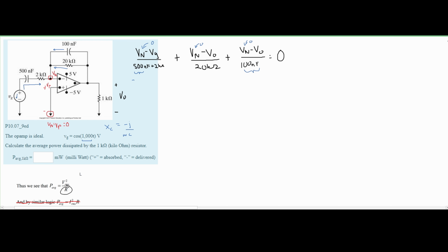We can write this as negative 2 kilo ohms, because the units is now going to be in ohms. That's what it would be when we do this conversion. And it's kilo because we have negative 2000. We know K is equal to 1000, and that's why it's in kilo ohms. Now we're going to look at the 100 nanofarad. It's going to be the same thing, negative 1 divided by 1000 times 100 times 10 to the negative 9th. And this is going to give us negative 10,000. We can also write this as negative 10 kilo ohms of resistance.